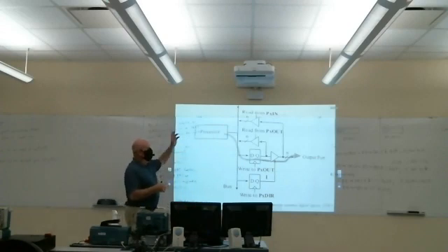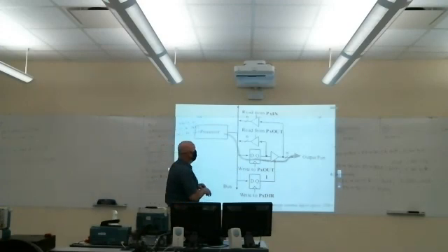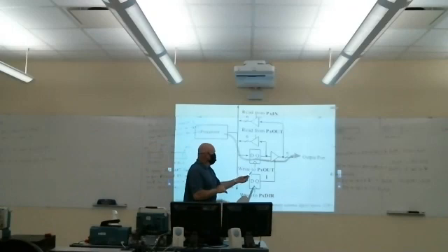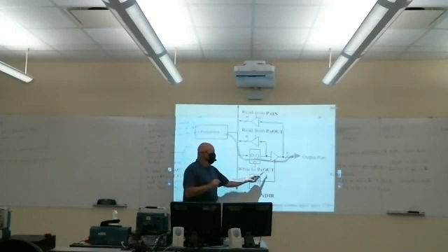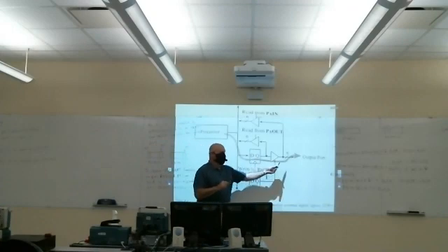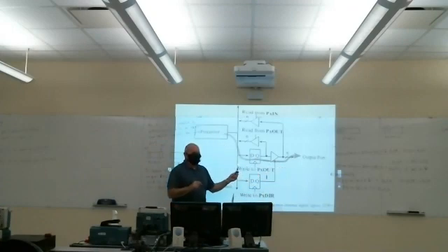Then now, just like to read from that pin, we read from the input register. To write to it, we write to the output register. So you would set that 1 bit, again, typically by ORing the output register, because we only want to affect that 1 bit, ORing that corresponding bit with a 1 to set it high, and then clearing that bit, ANDing it with a 0 to set it low.